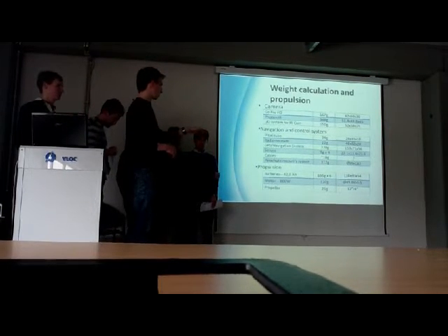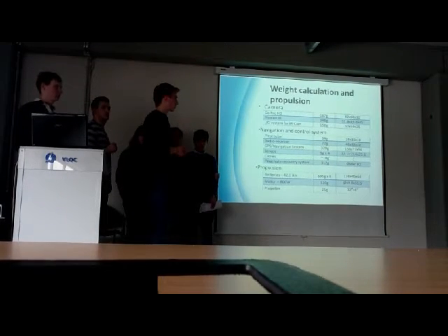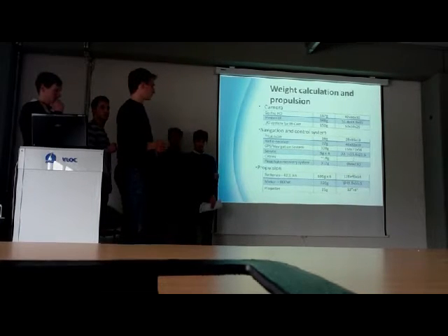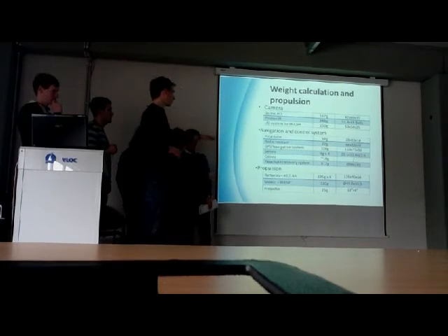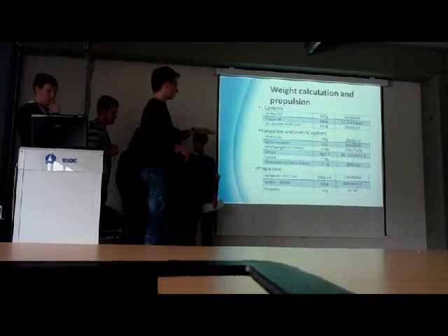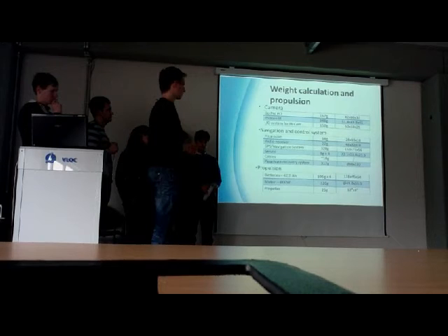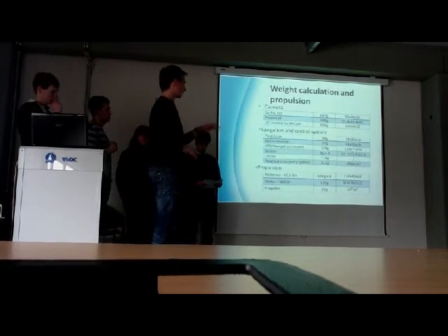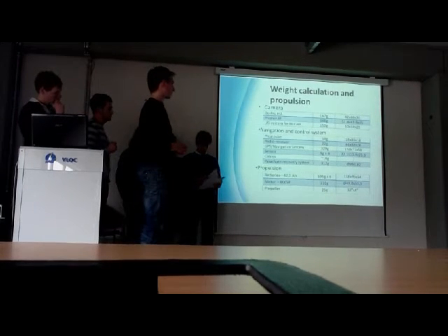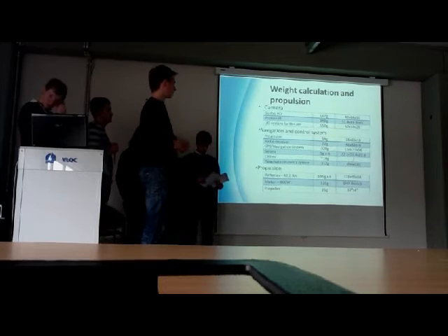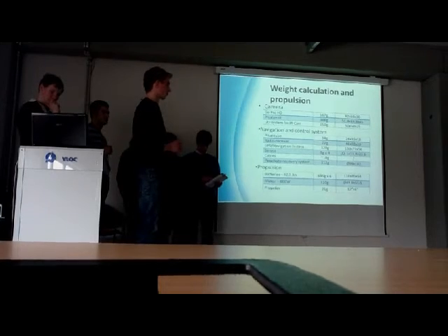We estimated all these kits through our free program, which is Drive Calculator. It's free. You can download it for free. And when we know how big the current is, we choose the biggest batteries, which are 5,000 mAh, and we calculate how many of these batteries we need for our whole flight.